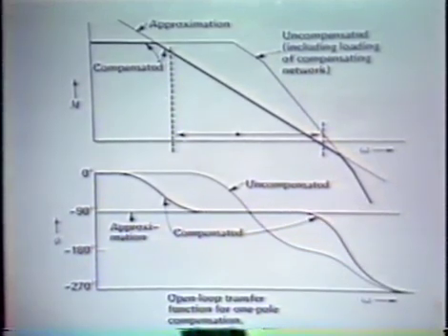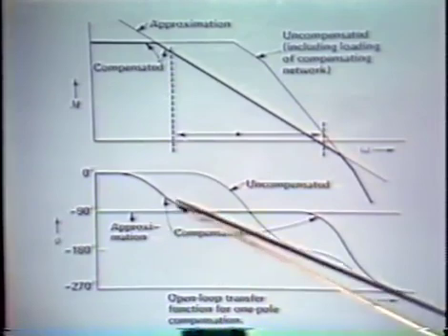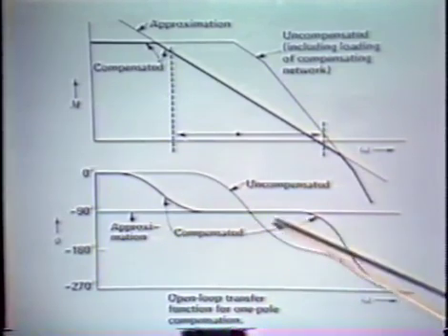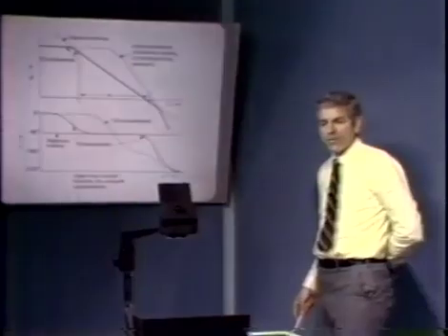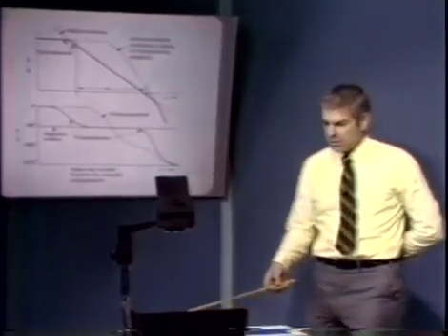So here we have a situation where the use of a single capacitor, and in fact quite a small one as we see, controls the transfer function over a very wide range of frequencies, and gives us an approximately single pole roll-off over a very wide range of frequencies.